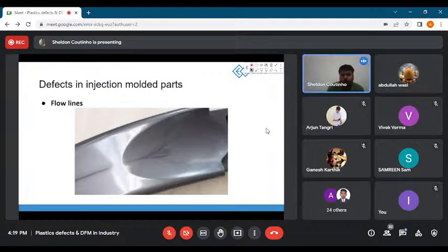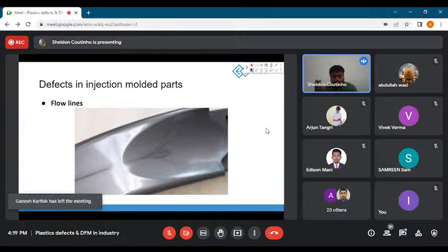Okay. So yes, Abdullah, it is not about the materials in this one. Basically, this is a homogeneous material, right? It is the same material throughout. What you're saying about this connection point is very relevant when we are talking about composite molding. Composite manufacturing is similar to the toothbrushes that you see, where you have your toothbrush body made out of plastic, and then you have a rubberized material. That is a composite, and that is where you will see a difference. If both are plastics, say one is a harder form and one is a softer form, there you may see some melting and this line occurring, but that is a weld line kind of defect rather than a flow line.